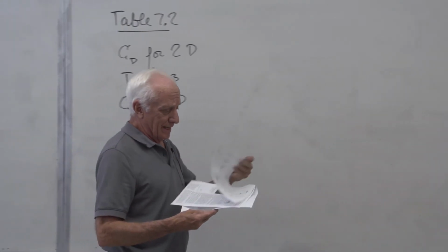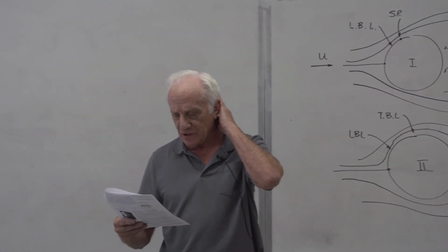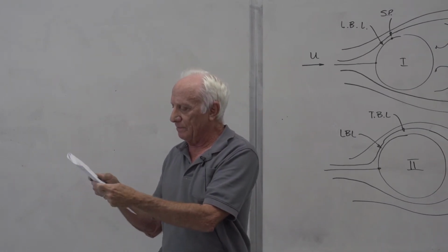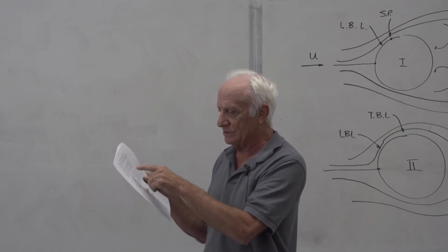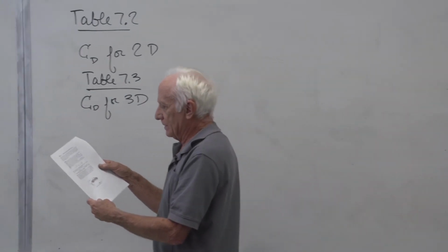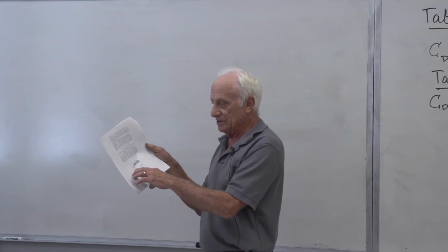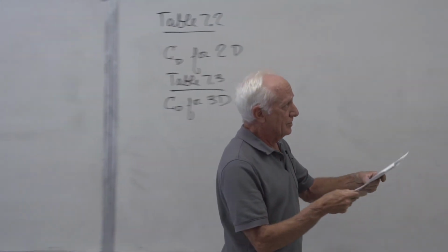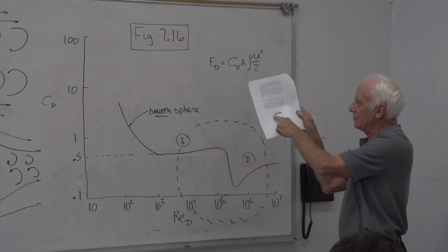And then you go to the last page there, measuring the drag coefficient of a car. It tells you how engineers can put a car in a wind tunnel. This is a full-scale test. You put the real car in the wind tunnel, crank up the wind tunnel to a certain speed, and measure the drag force with the instrumentation shown in the picture.